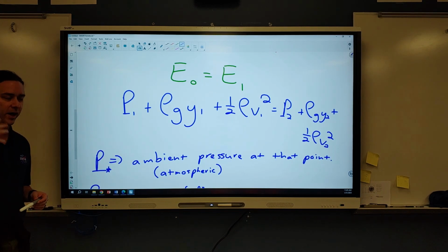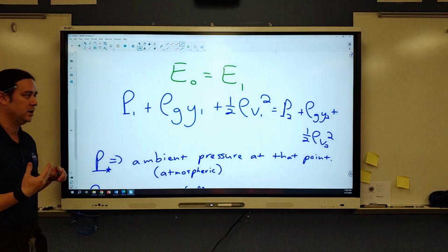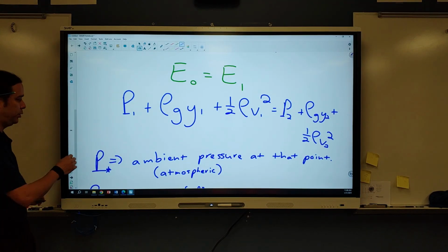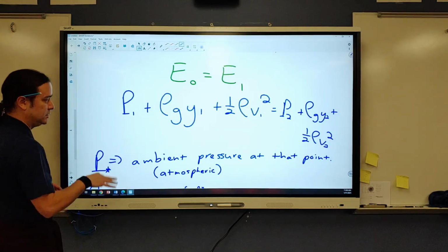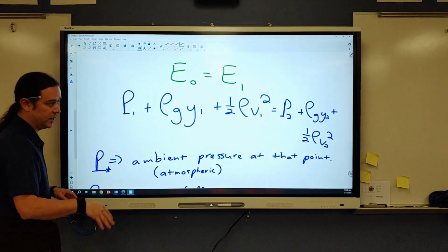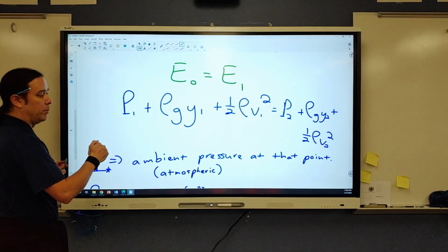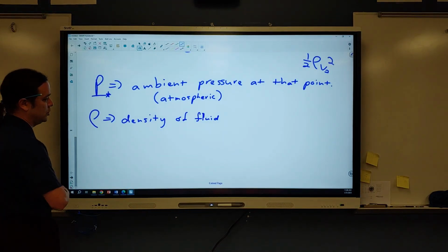I'm getting flashbacks to my aerospace engineering classes where we were warned repeatedly that Bernoulli's equation begins to break down, at least in the way that we were applying it, when the airspeed of the aircraft ended up above about 0.3 Mach. That's not something that you would need for my class or the AP exam, but I do want to bring this up, that as you go to the higher levels, this is an introductory class, but as you go to the higher levels, you might deal with compressible flow. And while Bernoulli's can apply there, it starts to get much more complex than this equation.